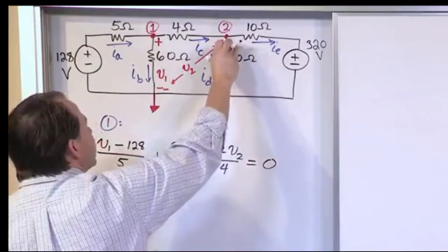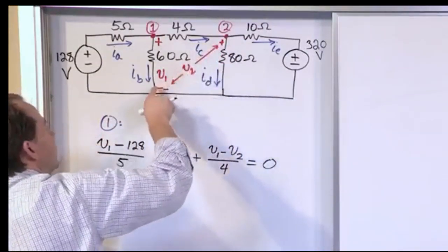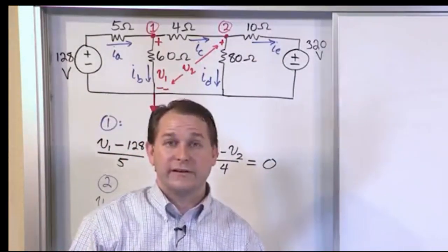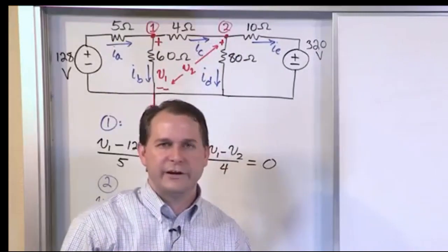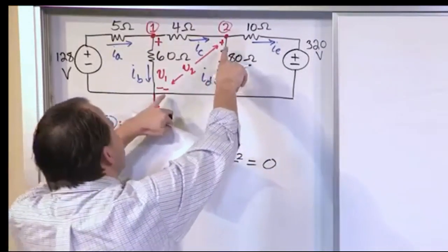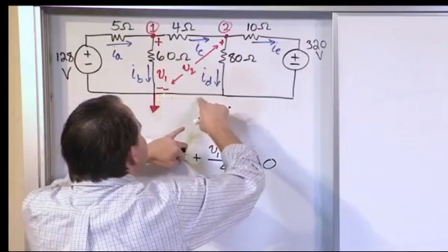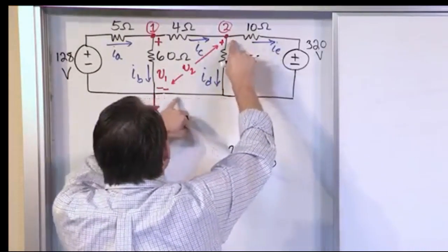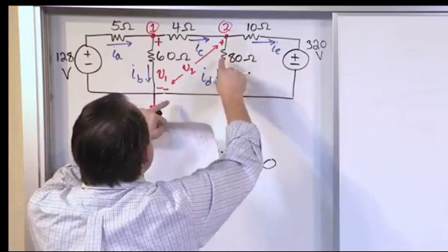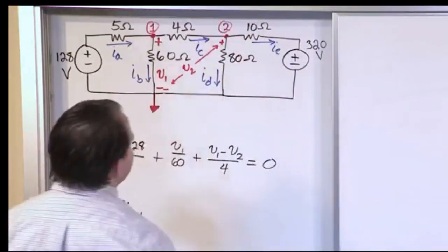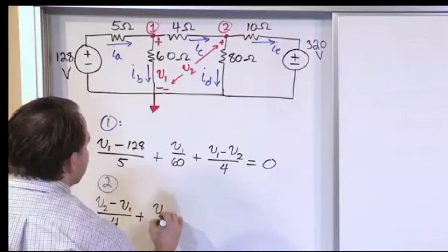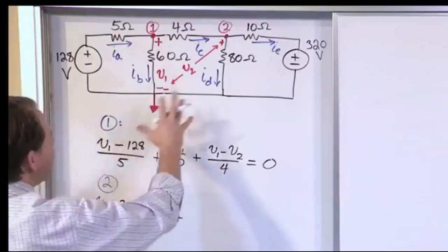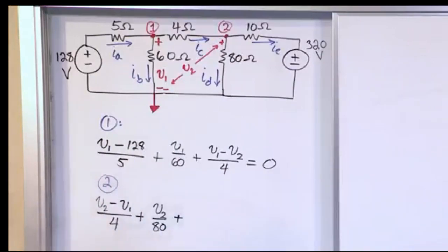But what is this voltage here? Well, this V2, this is another great example of when you need to have a little experience with circuits and sort of the real fundamental understanding of what it means. We've drawn V2 here, but don't forget this is physically connected here, so this voltage here is the same as the voltage here. It's all the same thing, it's joined together. So V2 really is across the 80 ohm resistor. So it's V2 over 80. I is equal to V over R. And that's not something that's given to you or told to you, that's something you have to just know from experience.